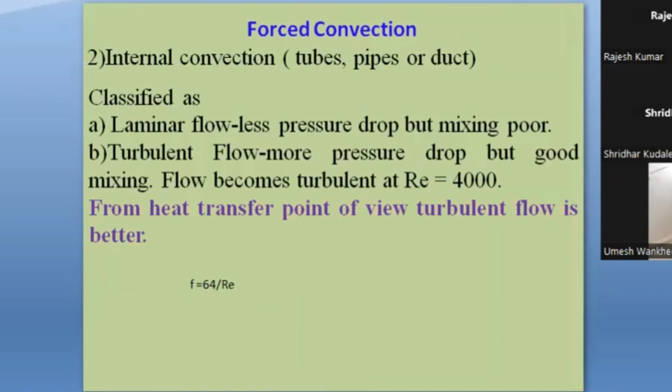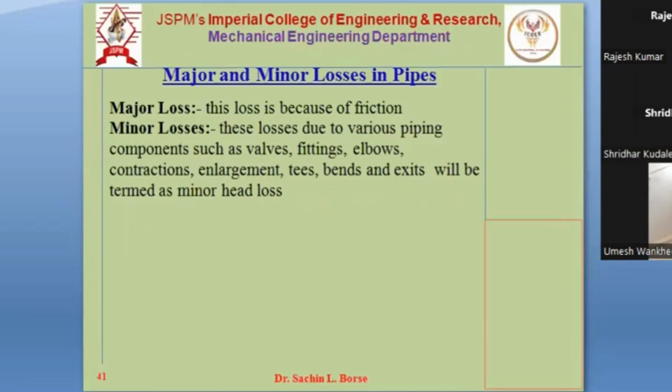So from the heat transfer point of view, we get more heat transfer in turbulent flow, and less heat transfer in laminar flow. Now, when we go for pipes, we also have to understand losses.